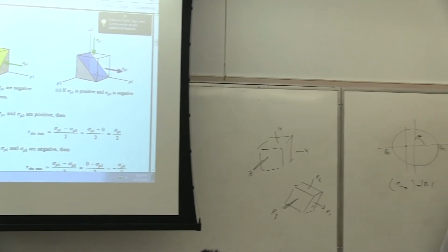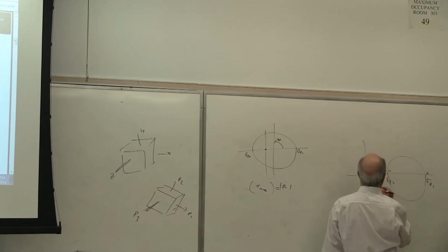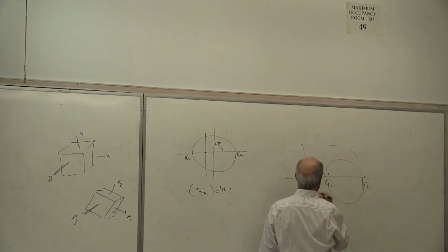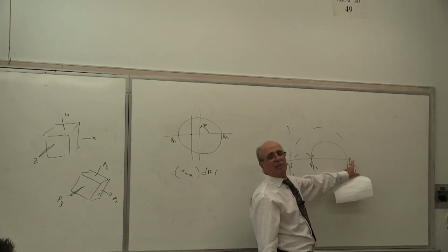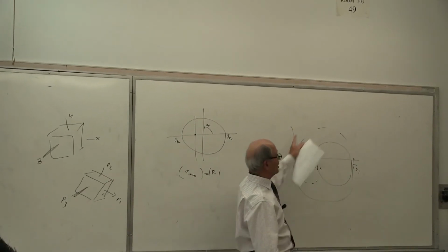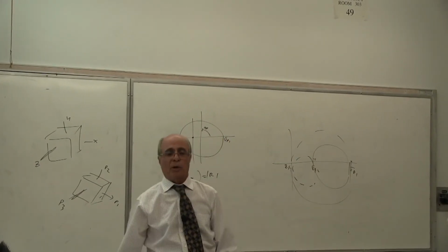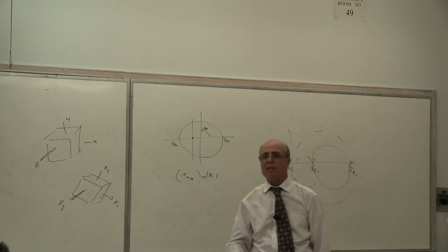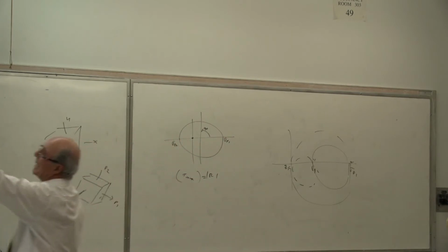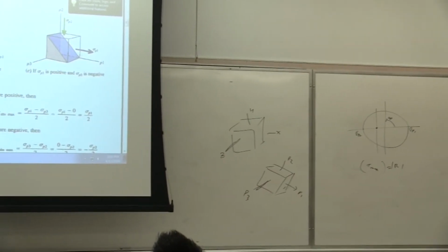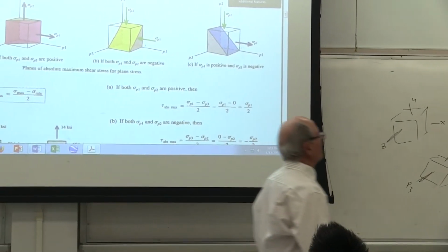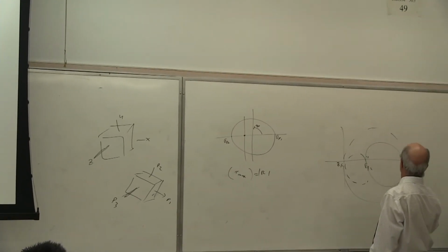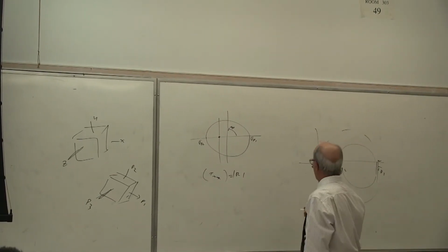So if this is the x and this is the y, and this is the z, therefore this circle is not important, that circle is important. Why? Now, what is the principle? What is the maximum shear? The maximum shear is this larger circle. But the circle is between what? X and z, so the rotation must be about the y-axis. It is in that plane, which is there somewhere going like this. Is that correct or not? Yes? And the value of that is important. The value of that is not this circle, but the radius of this larger circle, which I gave to you.